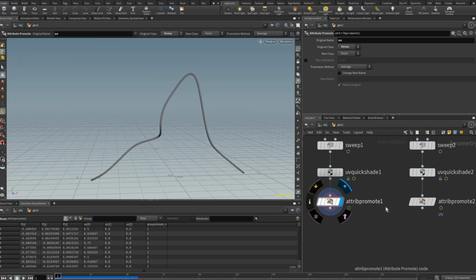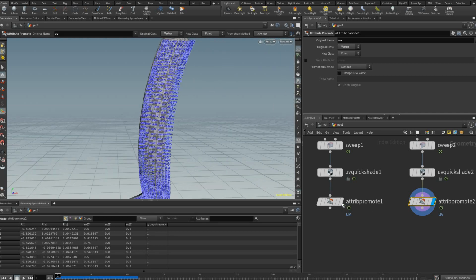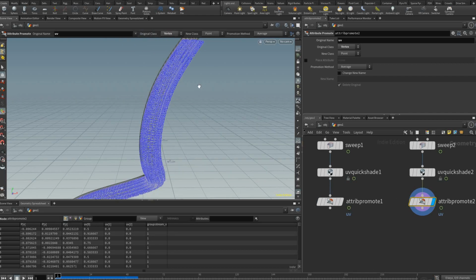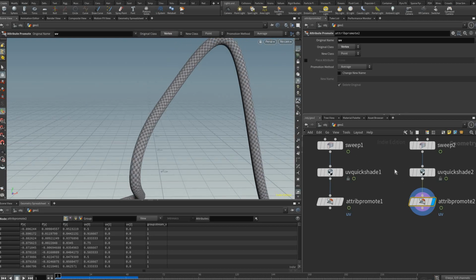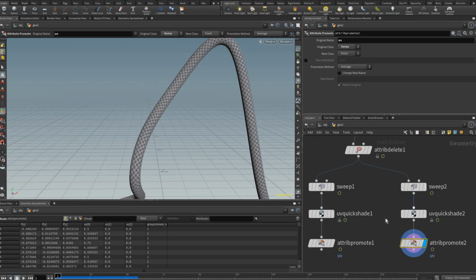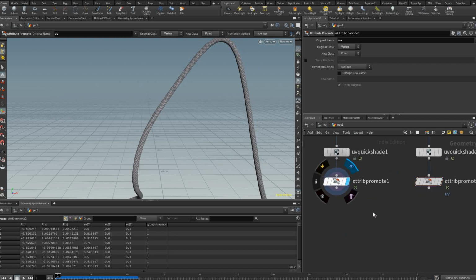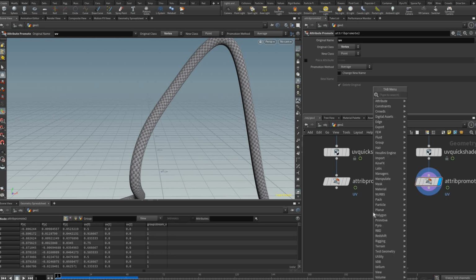Excellent. And now to make our shape, we're just gonna blend these two position values because both of these have the same exact point count, and the points are, if you look at the numbers, generally in the same location. This is why this will work quite well. And they should all be in the same location because we didn't do anything here that changes that. So to blend between these two positions, we're gonna create an attribute VOP, this guy right here.